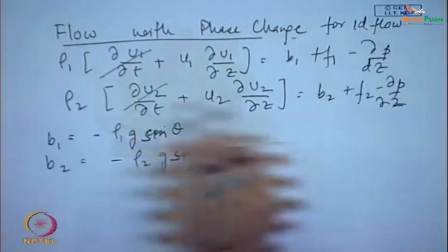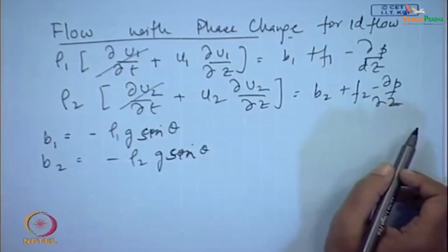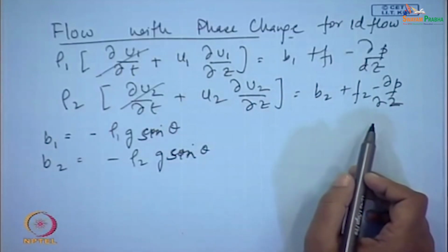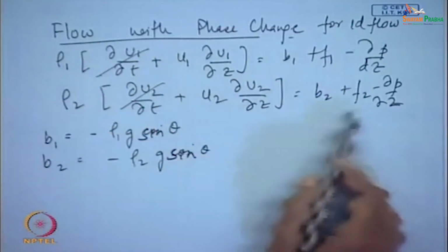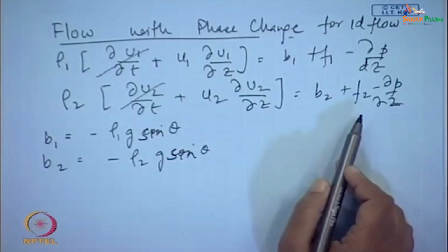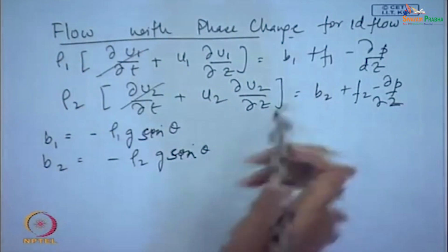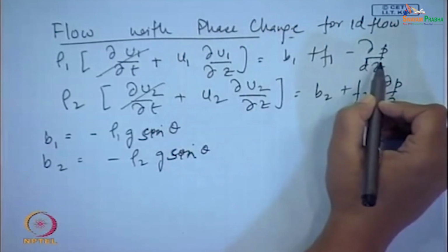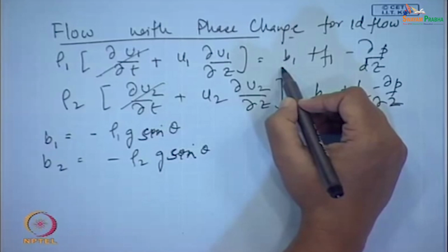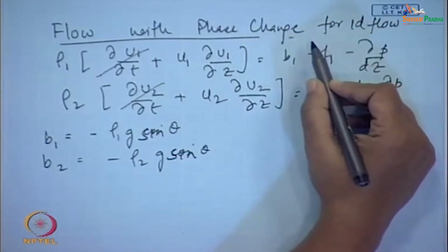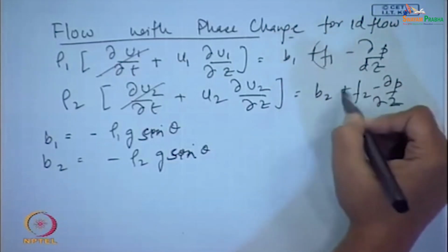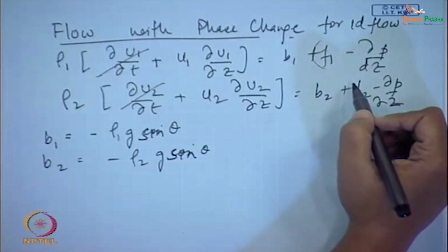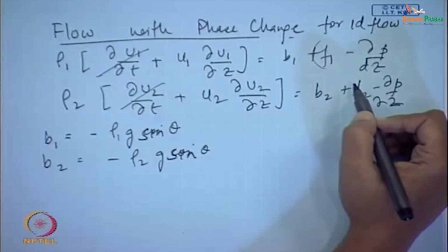So, remember one thing, these two equations are common for all two phase flow situations. We can also write down two such equations even when there is a drift, when the two phases have a strong coupling among one another, because we are just considering the two phases and writing down the momentum equation, is not it? But the important part here is that, in order to keep the account straight, whatever extra force which is not included in B 1, which is not included in pressure gradient, is included in F 1 and F 2. So, how do we account for different flow situations, whether it is a drift flux or a separated flow, F 1 or F 2 are going to be different. Even in separated flow, for annular flow, you will have one type of F 1 and F 2. If there is a fluidized bed, you have a different type of F 1, F 2. Is it clear to all of you?